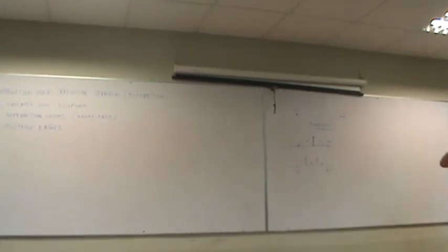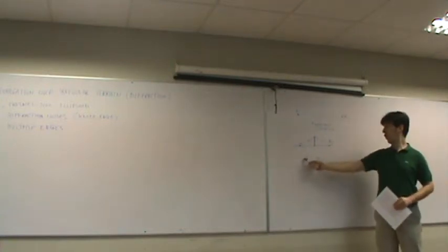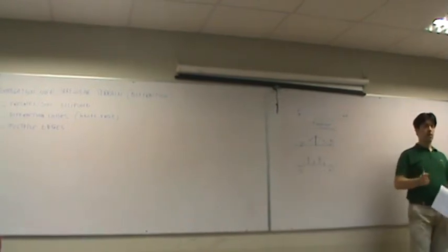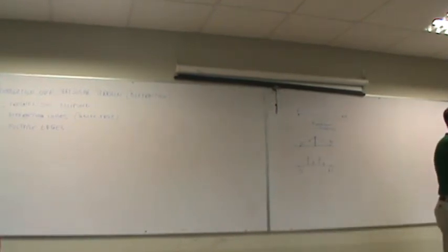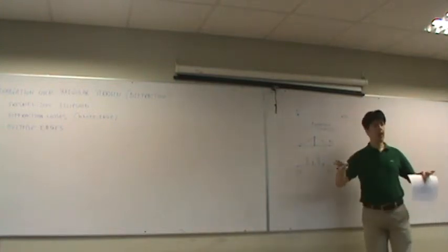You have several buildings, and you want to know the extra attenuation. In other words, whether it is easier to pass over the buildings or around them. You will see that quite often in an urban environment, losses are lower if you go around the buildings, if the transmitter and receiver are at ground level.